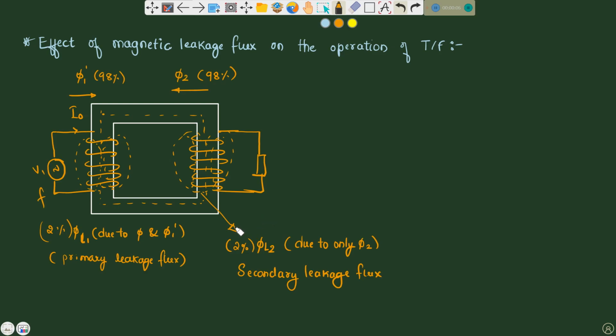So today we are going to discuss electrical machines for assistant electrical inspector and other various examinations. In that we are going to study the effect of magnetic leakage flux on the operation of transformer. How is this magnetic leakage flux in the transformer going to affect the operation? This magnetic leakage flux is the part of the load component of flux which links either the HV winding or the LV winding, but not both. Understood? So it is not having any role in transferring power from one circuit to another circuit.